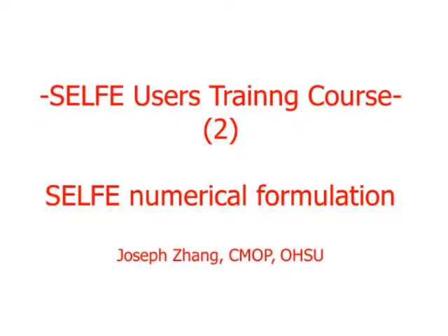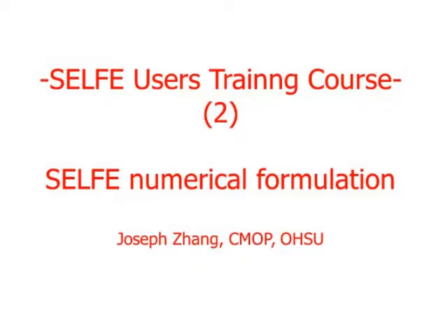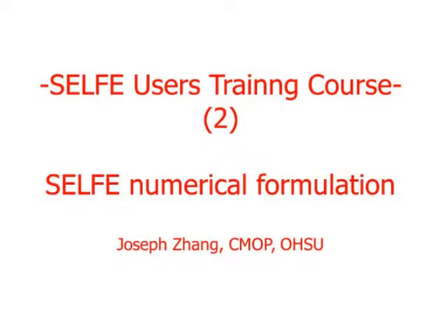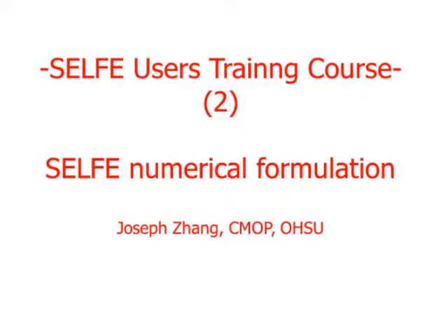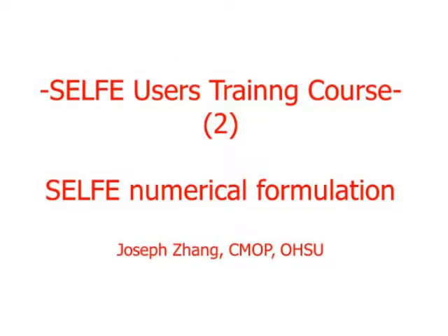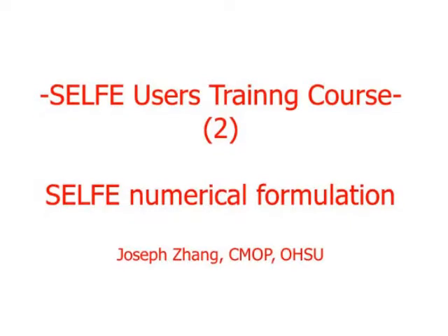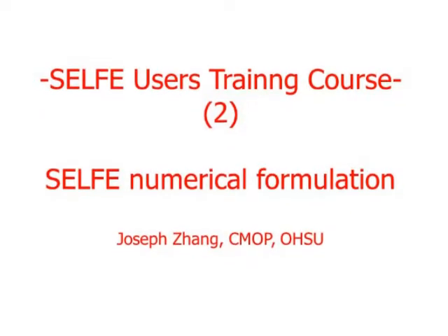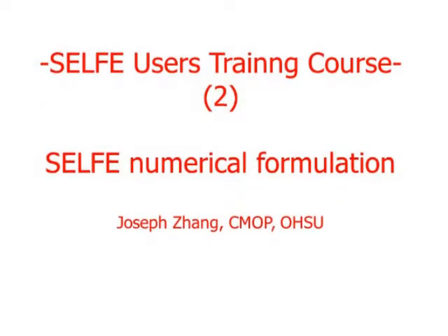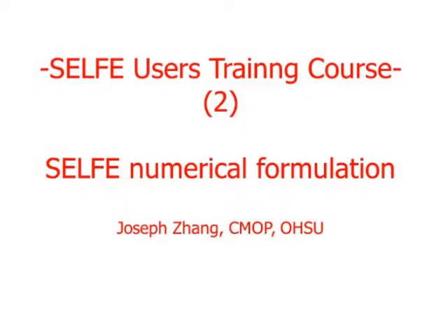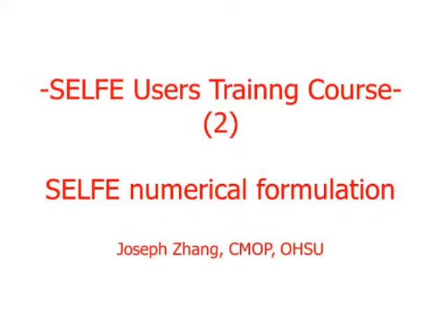That means phi i is 1 at the point where it's defined and 0 everywhere else. That's the definition of a shape function basically. And if you use a weak formulation, you also want to make sure that your shape function is smooth enough, because when you do integration by parts, you need to take derivatives of the shape function.